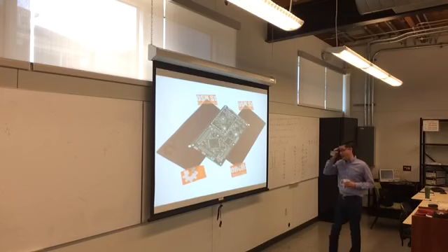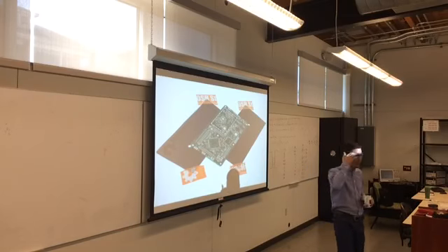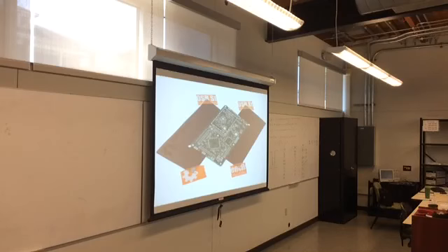Assembly. So you can put together your board however you want. If you've got a bunch of through-hole components, you just sit in the back there with a soldering iron, you heat it up, you solder it like you've always done. If you have surface mount components, if the pins are big enough and wide enough, you can kind of put some paste down yourself and hand solder them, or you can use a hot gun and put some paste down, put your part on it, hit it with a hair dryer, and there it goes.